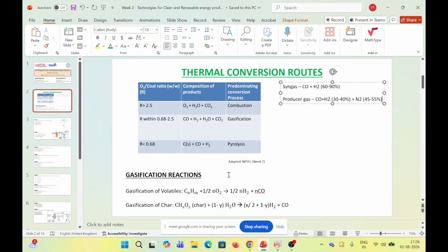However, the stoichiometric quantity of the hydrogen gas that gets produced through this is going to vary. So the gasification process as such comprises the following steps. First one is drying, second one is devolatilization, third one is reduction, fourth one is oxidation, and fifth one is ash cooling. So like any process, gasification comprises a series of processes starting from drying, devolatilization, reduction, oxidation, and ash cooling.